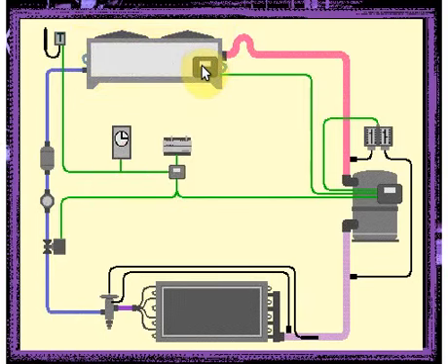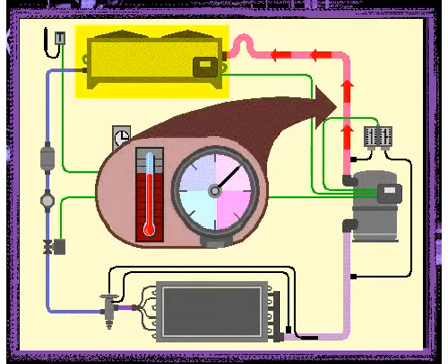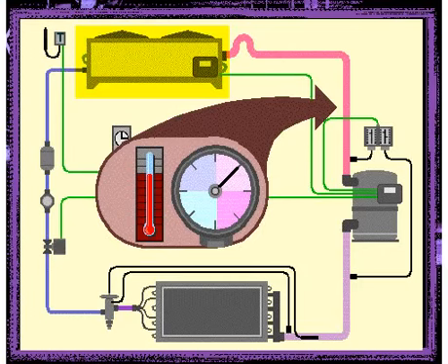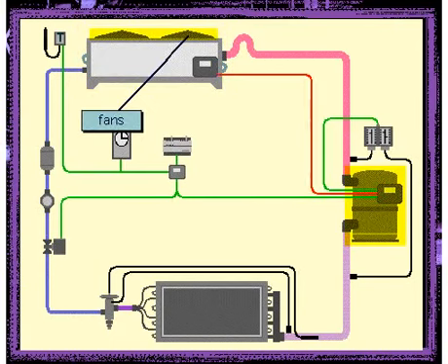In order to try to adapt to the variable flow of the refrigerant arriving at the compressor, some systems use multiple compressors. As the flow of refrigerant increases, the suction pressure increases, which in turn allows a larger number of compressors to start up. The condenser receives the gaseous refrigerant at high pressure and high temperature from the compressor. The function of the condenser is to condense the refrigerant in order to then return it to the evaporator. The compressor and the condenser fans operate simultaneously.